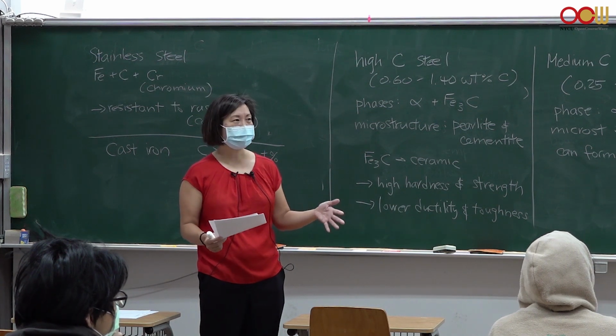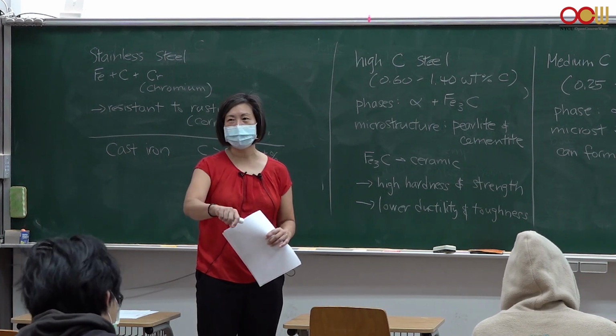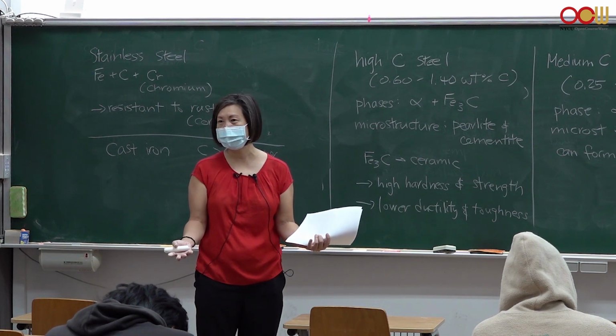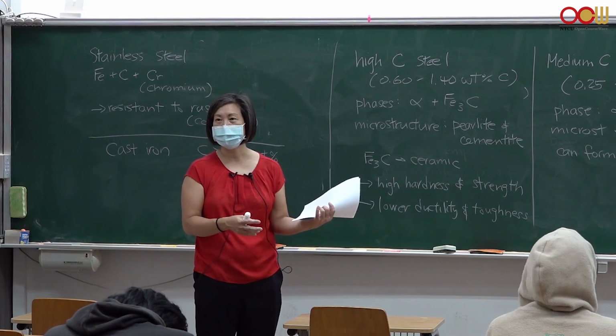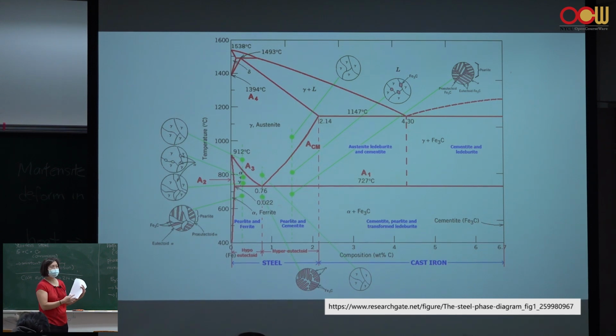And that's why it's called cast iron, because you can melt it and cast it. Casting is just taking a liquid, pouring it into a mold to form your solid. Okay, so cast iron is iron that's more easily cast because it has a lower melting temperature. And so cast iron, obviously, has a different microstructure because it doesn't go through the pure austenite phase, right? When you're solidifying it, lowering the temperature, it goes into the austenite plus cementite phase before going into the ferrite plus cementite phase. So it's going to have a lot more cementite compared to your lower carbon steels.